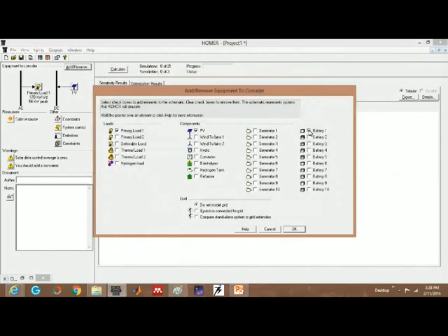So I can go for battery. And here you can find three main features on this screen. One is do not model grid, right? System is connected to grid, and compare standalone system to grid extension. These are three different case studies we can do with this Homer. Do not model grid means this is a standalone system. We are not connecting this to the grid.